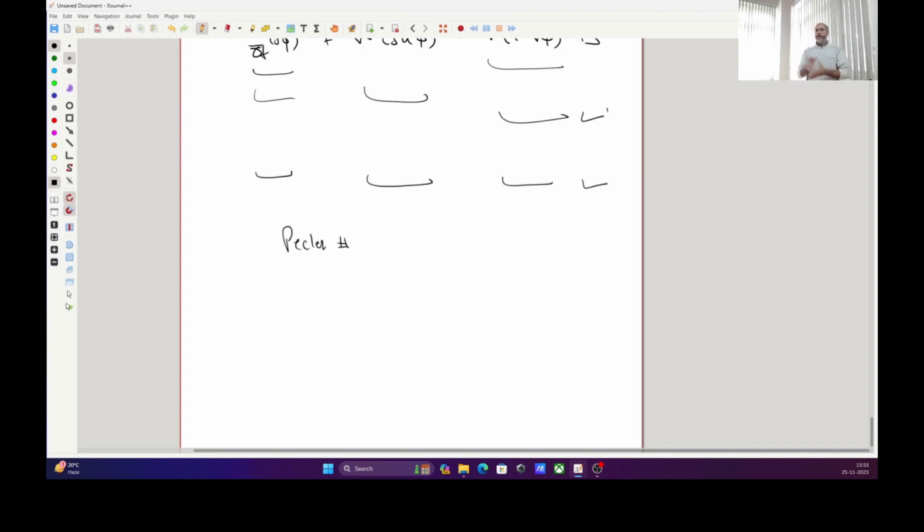Now we worked with nicely Cartesian grids, but in commercial software or open source codes, you saw that they were using triangles or triangulated grids, or tetrahedrals in 3D. And in reality, we work with unstructured grids in practice. The reason is because complex boundaries can easily be taken care of. And you saw mesh adaptivity, where you have these really elongated grids and so on. So with Cartesian, that becomes a problem.